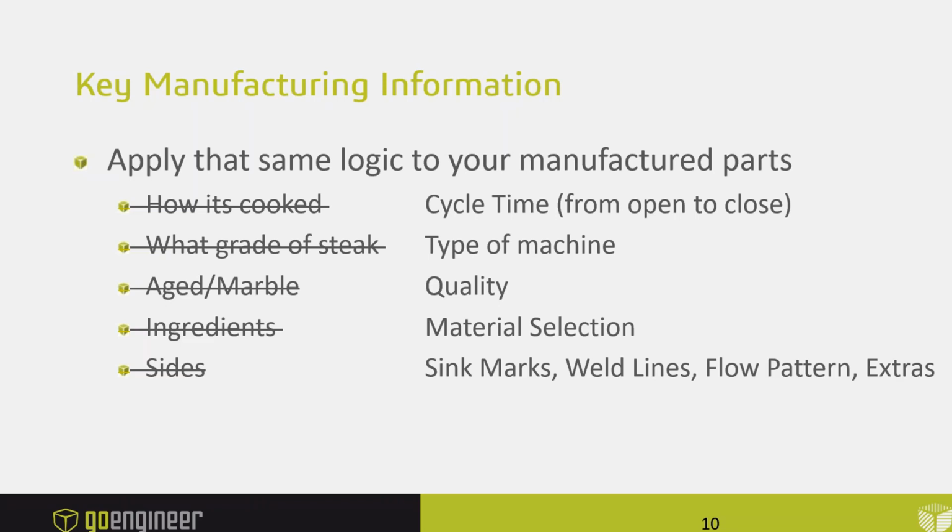What's the quality like, right? So with plastics, we can look at the quality ahead of time, right? To look at the weld lines, sink marks, and I have some great examples of what these look like. But do you need someone at the machine, operating the machine, or is it going to run 24/7, right? Or do you need an operator there to pull the parts out and inspect them and put them in a go no go pile? You shouldn't have to do that.